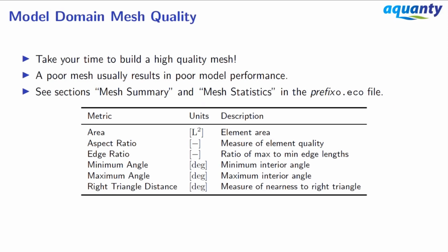And as Brayden touched on in his portion of the talk, you should really take your time to build a high quality mesh. A poor quality mesh may result in poor model performance, and by that I mean numerical instability or slower run times.